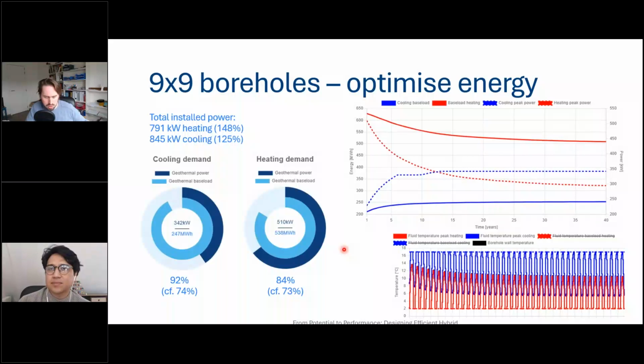This is how designers can use these optimizations to find the trade-off, which is really country and project specific, between the size of the borefield on the one hand, and the size of the ground source heat exchanger, or the passive heat exchanger, and ground source heat pump on the other, where the trade-off is between the investment cost there and the operational expenses from the energy component.